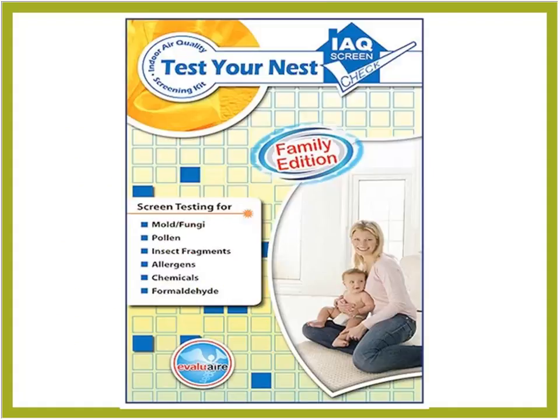One of the first things you can look at, especially on an existing home, is doing an indoor air quality test. This is growing in popularity, similar to doing an energy audit. It gives you the information you need to figure out what's going on in the house and help your client make reductions. Screening for VOCs, total VOCs, carbon monoxide, carbon dioxide, other particulates, allergens, chemicals, pollen, mold, you name it. You can really figure out what's going on in the house and then put a plan together on how to get rid of it.